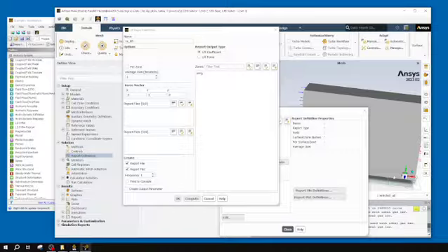For my lift coefficient, it's going to use those reference values that I just double checked. The bottom of the coefficient of lift is 1/2 rho v squared times A. So that's why we need to define those.